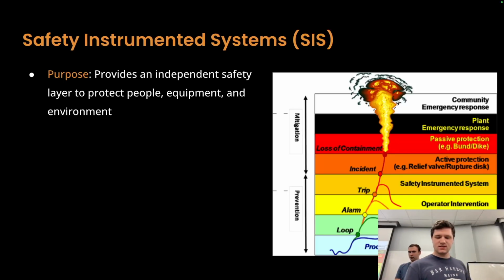You can see from the photo on the right how blue is the process design, which makes it pretty easy to know when to implement safety. Then there's process control, and then operator intervention, and then the safety instrumented system is your light orange layer, right before you really have to bring in a lot more mitigation. It's that last layer of prevention before you have physical damage.